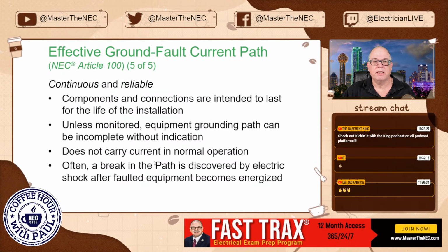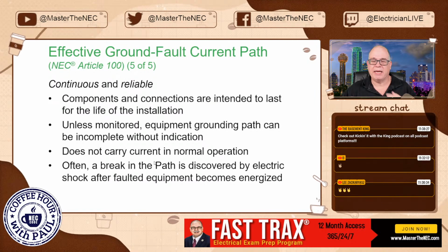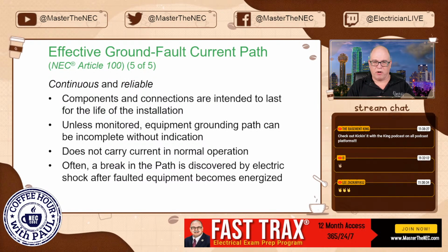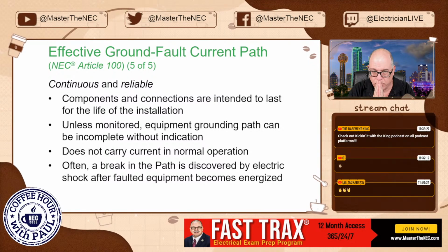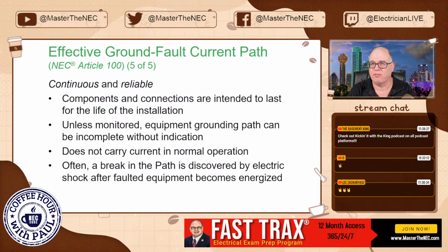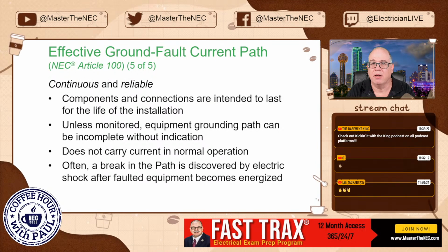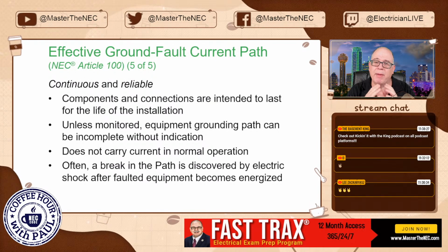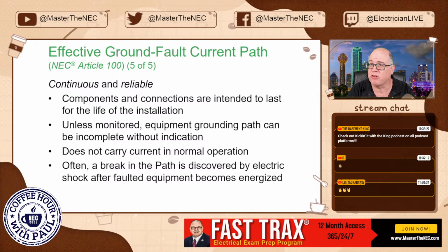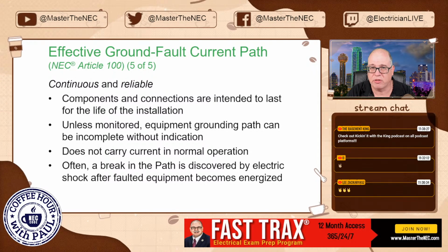All right. Continuous and reliable. Again, when we install an effective ground fault current path, the equipment grounding conductors, here's something you need to remember. We're not doing this temporarily. So when you make all those connections and you torque them and you do everything, remember, you're making this connection for the life of the installation.